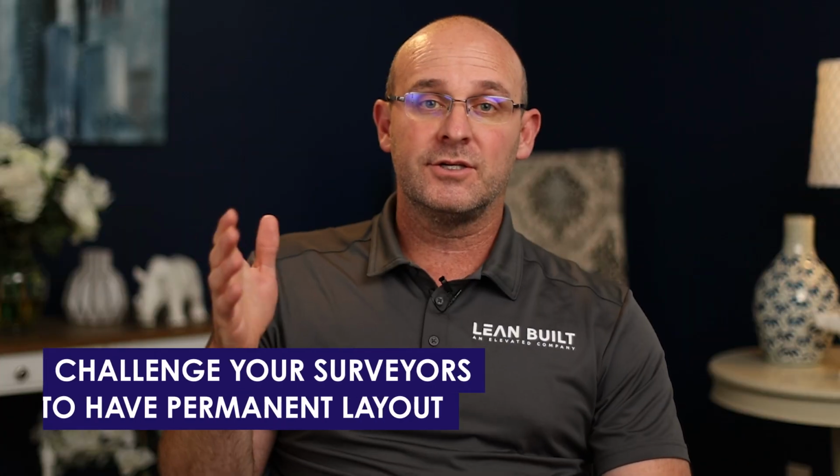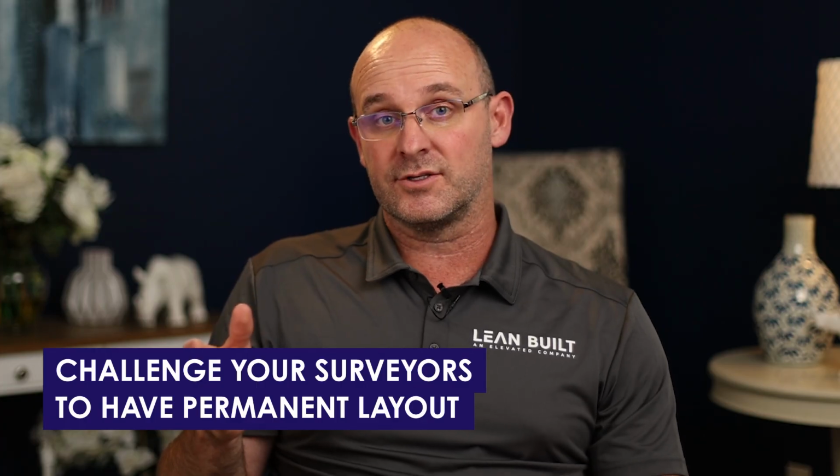So a minimum of 2. And here's what I'd like to do. Challenge your surveyors to have permanent layouts. So instead of just doing stakes with probably 60 penny nails, maybe even not doing hubs, try to put in more permanent monuments. Try to put in metal stakes, a point on the top of a piece of rebar with a cap, whatever you need to do to make it permanent. I like to embed those down like 2 inches below the surface of the soil so that I can just put a sandbag over the top, try and protect them as best as I can, put the stake, instead of vertically, go ahead and nail that down to the ground.